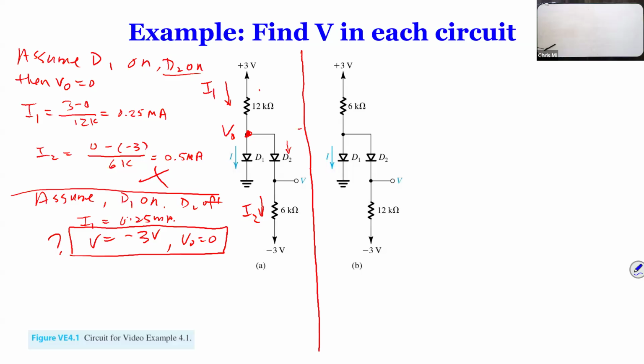Yeah, because there could be a voltage drop across D2, it's in the opposite direction, right? No. Why? Well, you said D2's off, which means that D2 is off. But this is -3. So you have 0 - (-3). So you have 3 volts on the diode, which is not possible. You have 3 volts across the diode, not reverse, because the bottom is negative, the top is 0. So 0 minus -3 is 3. You have 3 volts across the diode, which means not possible.